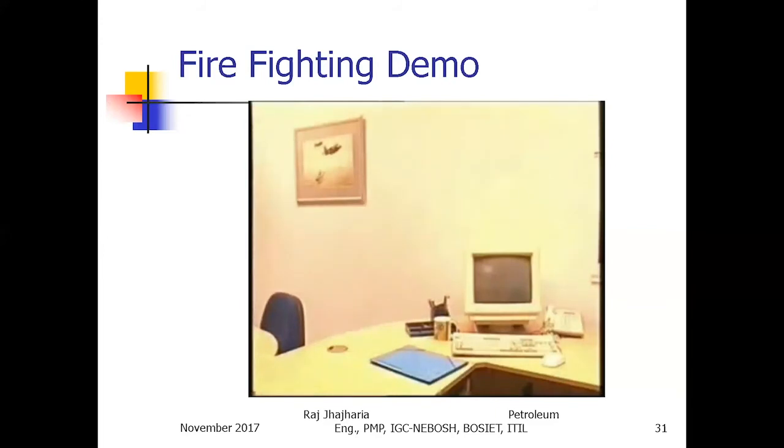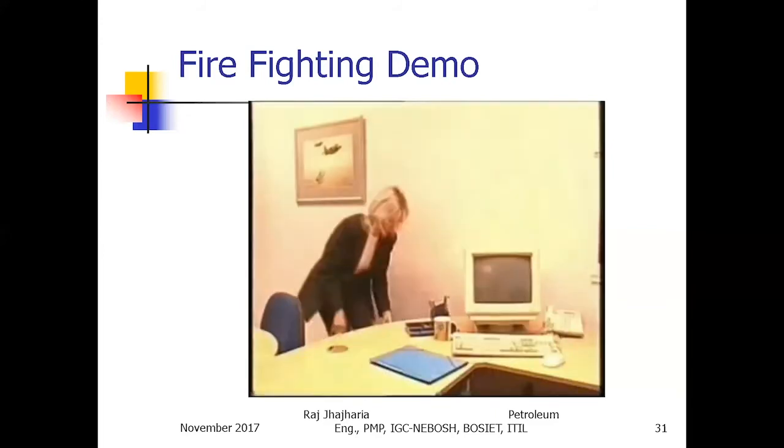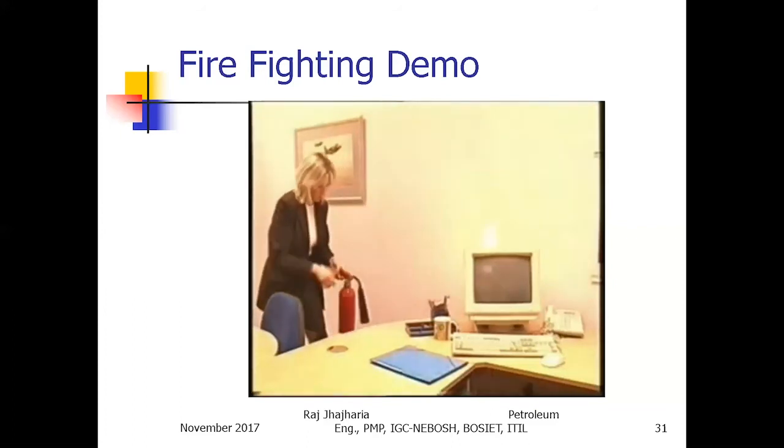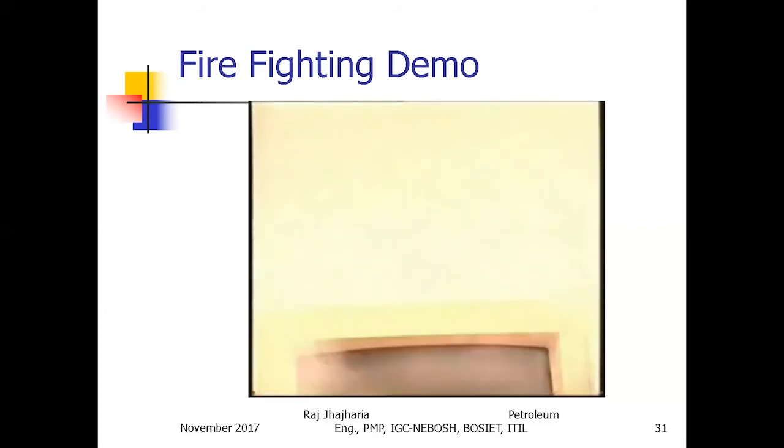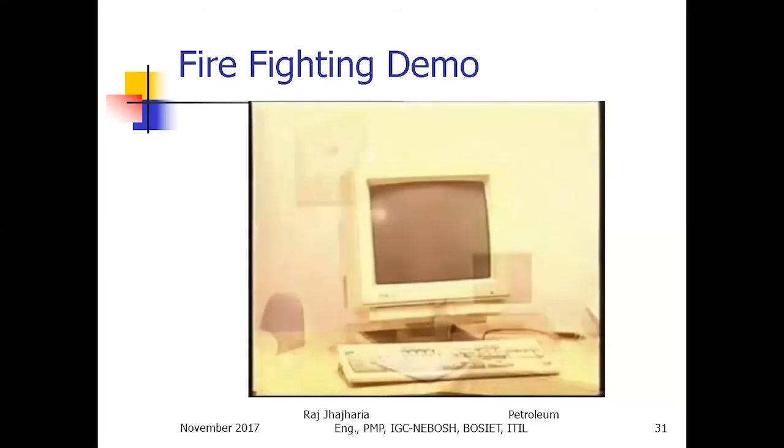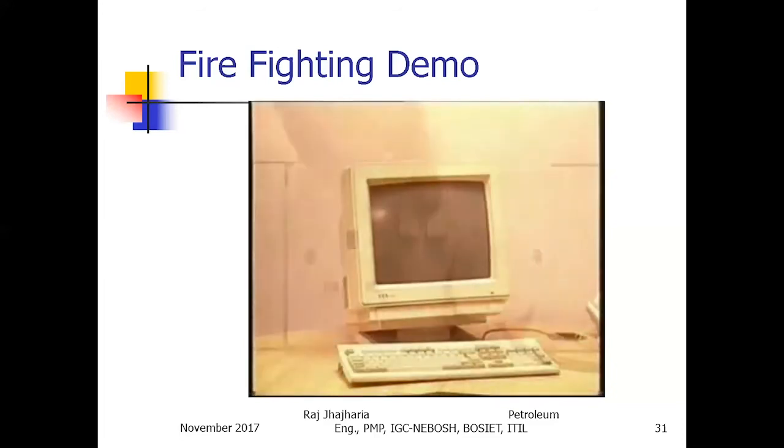If you find yourself confronted with a fire like this, whenever possible, switch off and unplug the appliance. The CO2 should be applied through any available opening until the fire is extinguished. The reason for switching off and unplugging first is that electricity provides the ignition source to start the fire, so once it's been removed, the fire may well die out of its own accord.